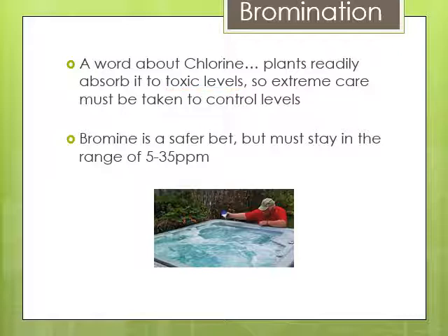So you can treat the water and it will stay in the water, but you don't want any more than 35 ppm (parts per million) bromine in your irrigation water. So growers that use bromine have to do water tests daily to make sure that there's nothing wrong. Because if you go above that, you could kill all the plants in your greenhouse. So that's just another job for the grower to check on in their daily routine.